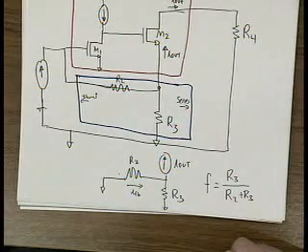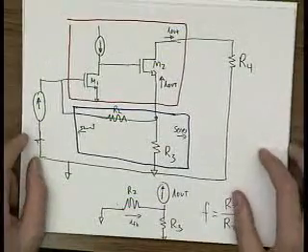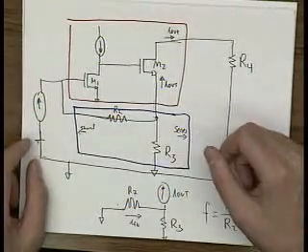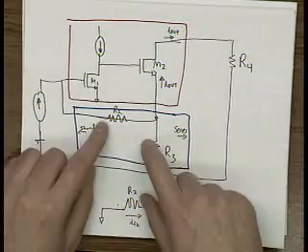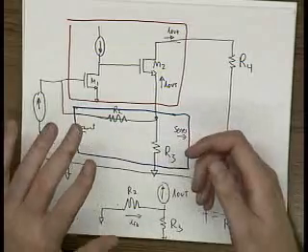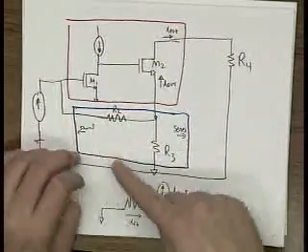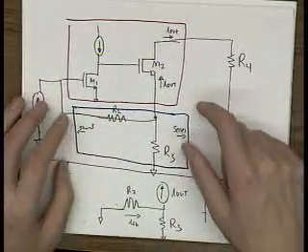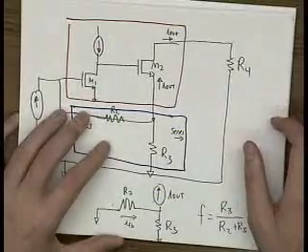Okay? And we can do a similar sort of exercise with A to calculate what the forward loop gain is. Okay? And the thing is that in order to formally calculate what A is, you need to keep in mind that this resistor network loads both the input and the output. But I don't think Professor Broderson has got to that yet, so I don't want to get ahead of him in lecture.